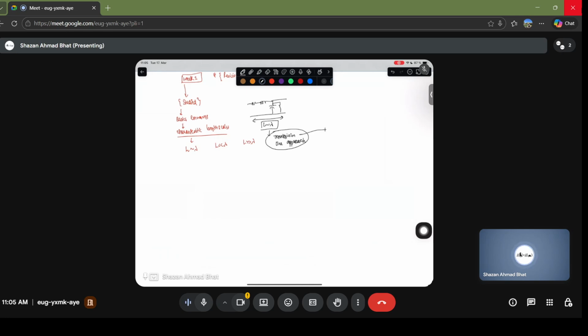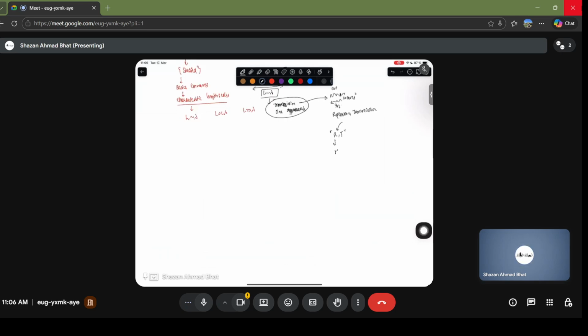And in the transmission line approach, you have to treat it as if there are electromagnetic waves flowing through the circuit. There is the outgoing wave, there are incoming waves. You need to talk about reflections, you need to talk about transmissions. So essentially what you studied was the reflection coefficient, the transmission coefficient, which you denoted by gamma. That is the essential part of this transmission line approach.